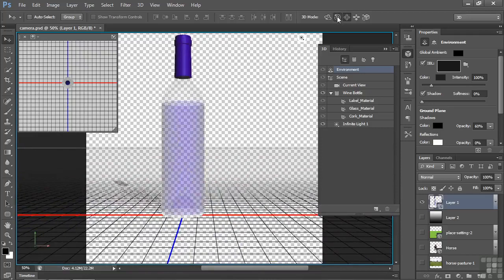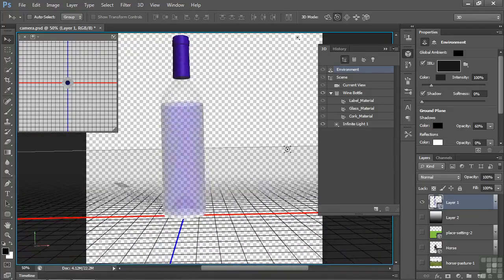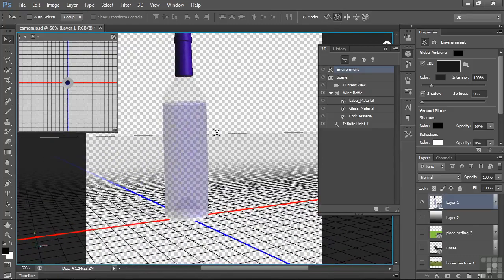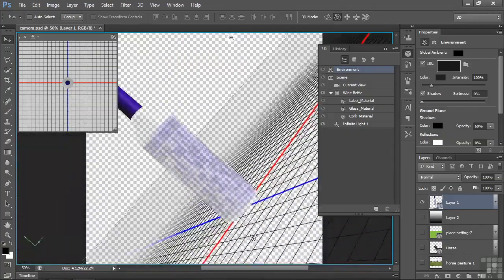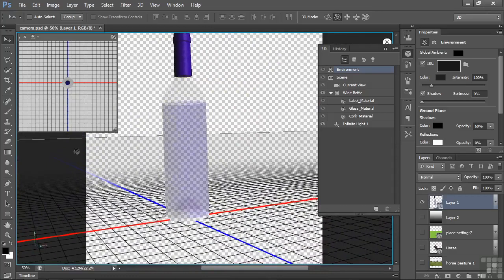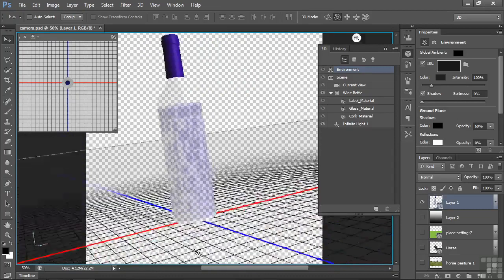This one's called roll. This one's called rotate. What's the difference? Roll rotates the ground plane on a distant place, way off there in the distance. It's not necessarily the end of the z-axis. It's just the farthest place there in the back. It rolls it on that faraway place. So if I go like this, it rolls it over there. If I take the rotate tool, which I'll explain in a moment, and rotate the whole ground plane here, then go back to roll, it's still going to roll in that distant place. It's always based on the current view. It's always that place off in the distance that you're rolling the entire ground plane. It's not on the z-axis per se. It's just on that distant point over there, straight back from the viewer. That's how the roll tool works.